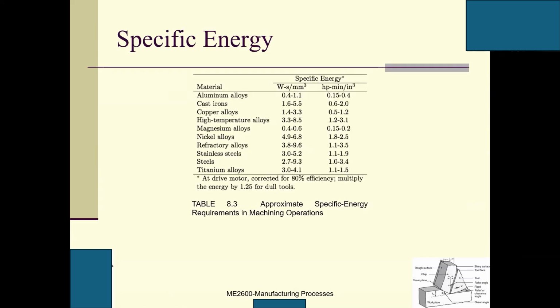Are you confused? Question? Back to the dynamometer that you're talking about, that just measures torque and stuff, right? Yeah, the dynamometer is used to measure the cutting forces, how much force you apply in three directions, X, Y, Z. With the dynamometer, FC and FT can be directly recorded. However, the shear force and normal force cannot.